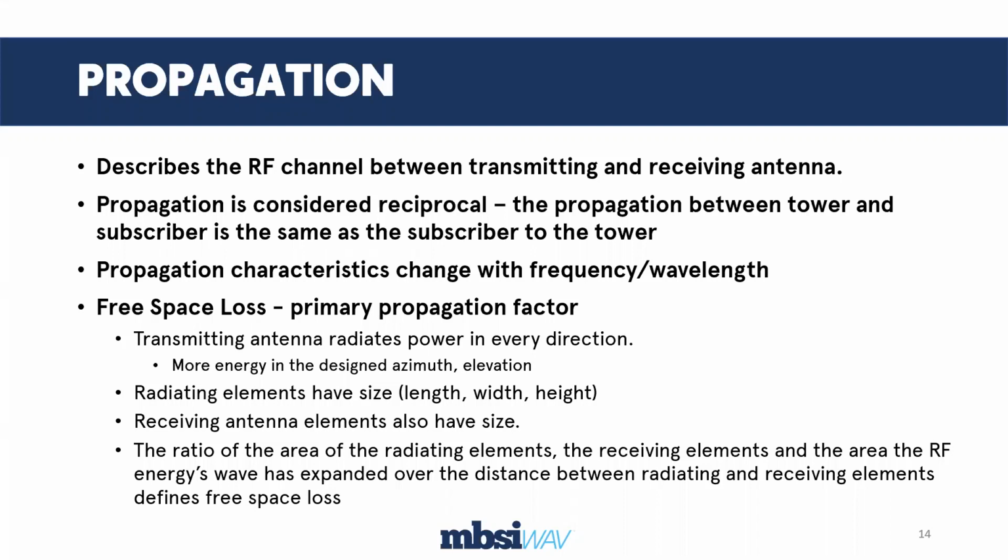Propagation through the air or through free space between my antennas is reciprocal. If I have so many dB of loss between the tower and the CPE, I always have the same amount of loss between the CPE and the tower. So both directions, exactly the same.